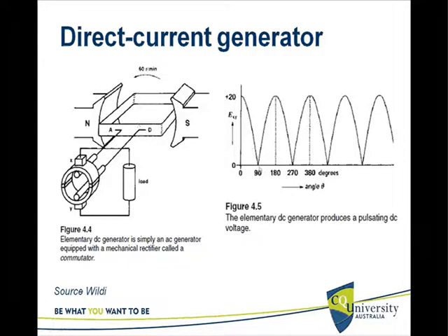As you could see, when the winding is at 90 degrees or 270 degrees, it is generating 0 voltage. So in this arrangement, the key thing is to place the brushes in this 0 position, which is the vertical plane in this case.